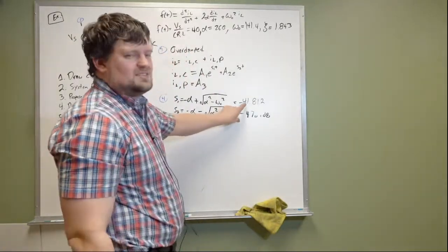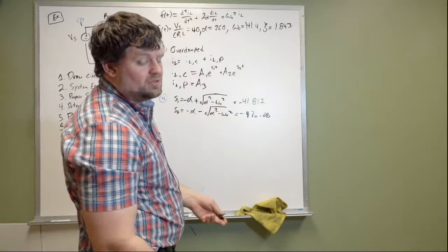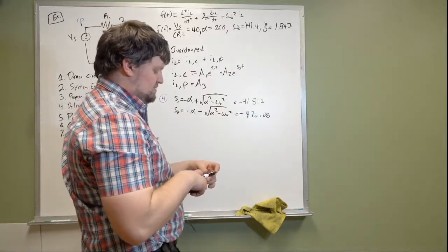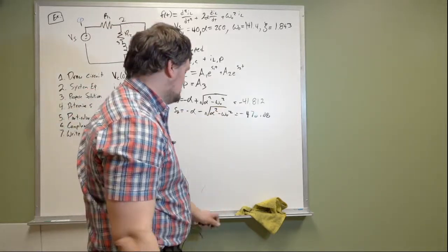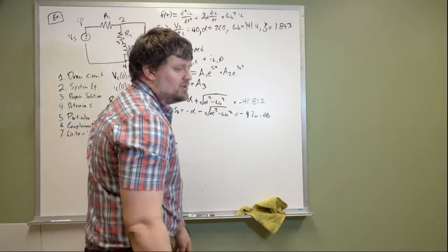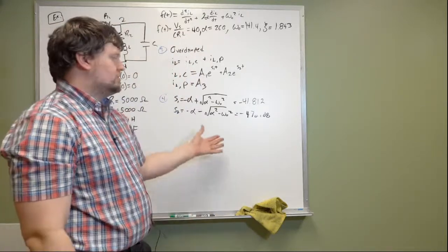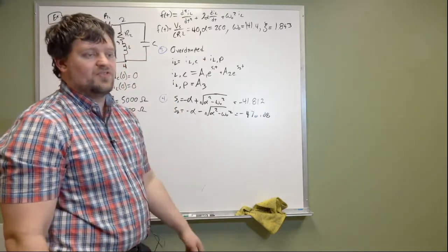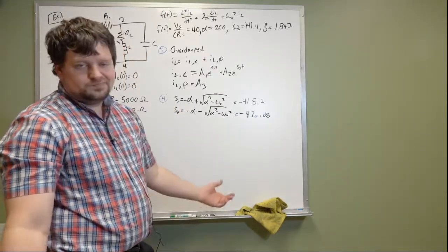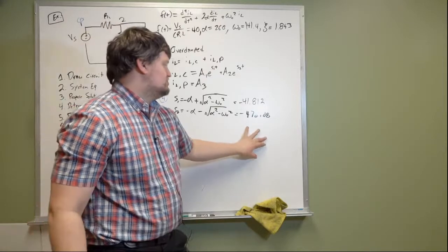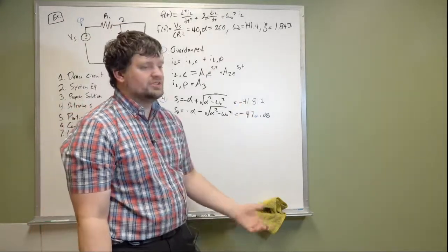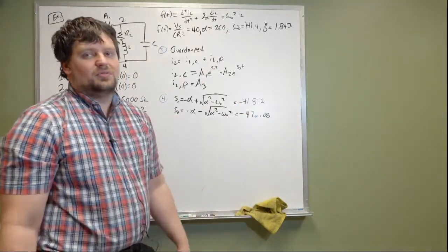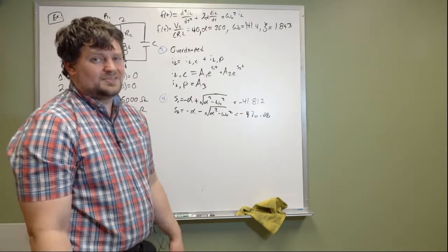Now these are actually fairly large S values. What this means is that this is going to reach equilibrium very quickly, comparatively. Now we could tweak this to reach a critically damped system, and then it would reach equilibrium even faster. But as it is, because these values are so large, it will reach equilibrium more than likely within a second.